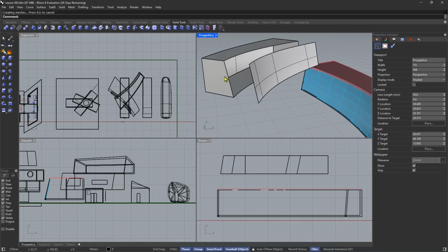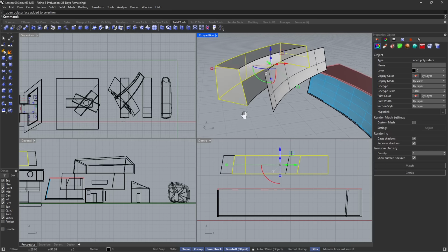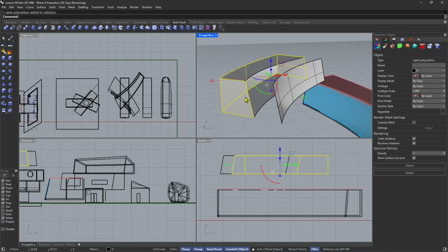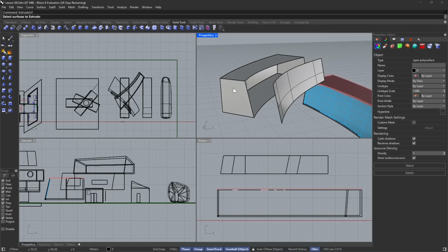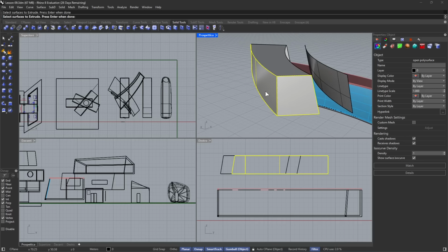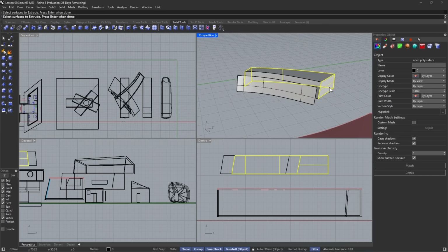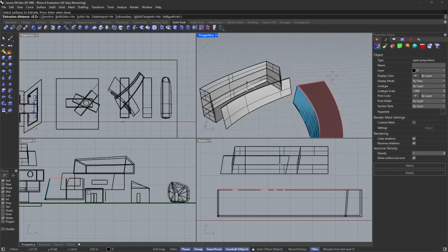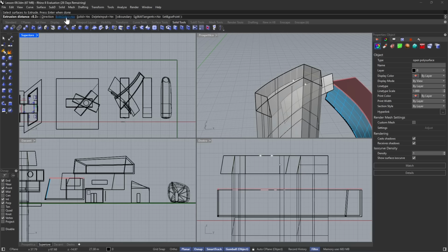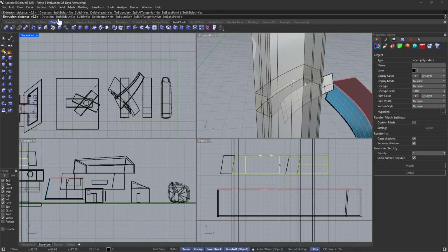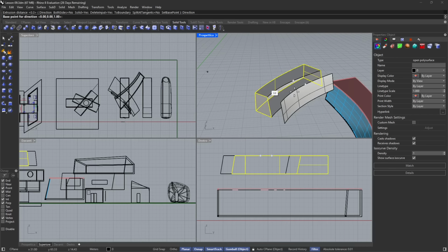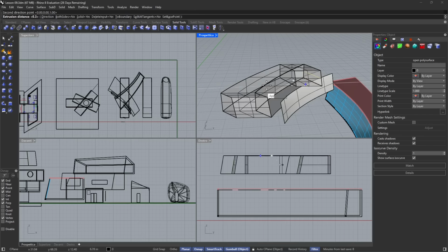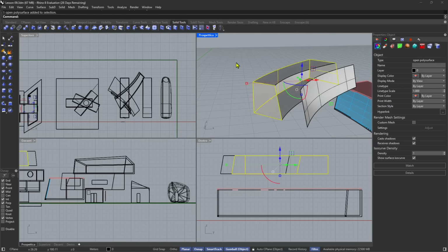Now, when you have a situation like this, with a polysurface, you cannot simply extrude. If you extrude, let's say I select these three again and press enter, you will see that they go in one direction. Unfortunately, there is no possibility here to move them. Well, we can do both sides, but this doesn't change the problem. We can change the direction, we can set our custom direction, but wherever we go, you see that they move in the same direction, which is not really a great result.